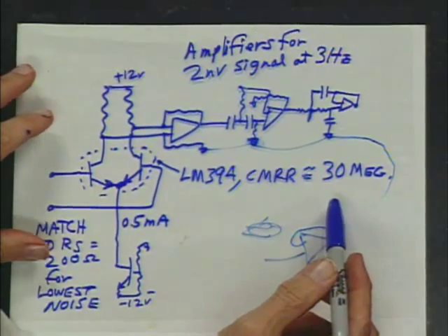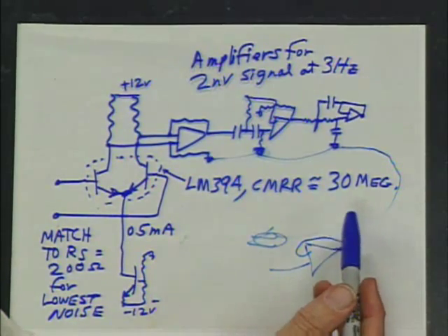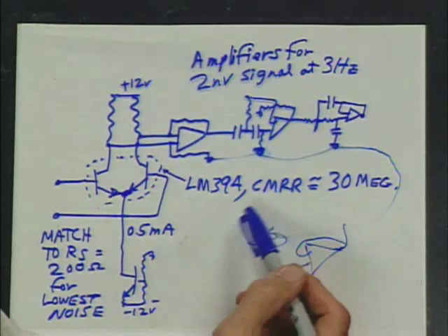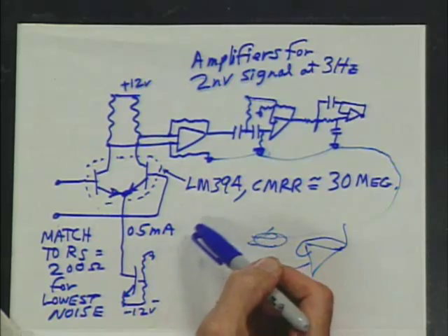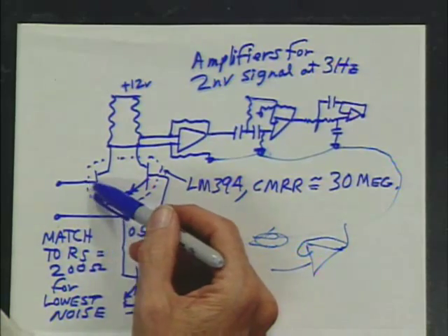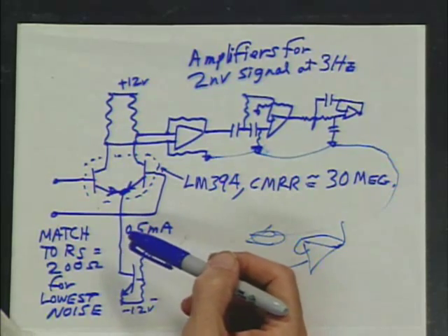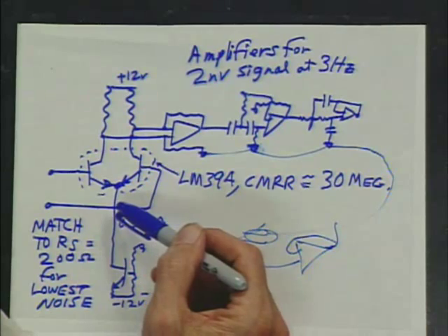Now, we usually say, what questions do you have? The question we have now is, what is the best way to make a low error amplifier? Well, we take the LM394, which has low noise, very low voltage and current errors. What's the voltage noise? Small. What's the current noise? Small. How do we compare the voltage and the current noise times the RS? How do we do that?